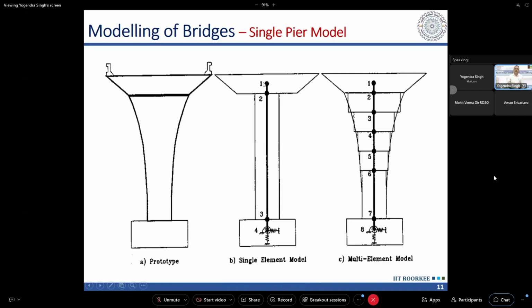If we have a normal simply supported bridge in which one end has fixed bearings and the other end has roller bearings, then in the longitudinal direction, the whole mass of that bridge will be lumped to the pier to which it is connected in a rigid manner. And the other pier will be relieved of that mass.